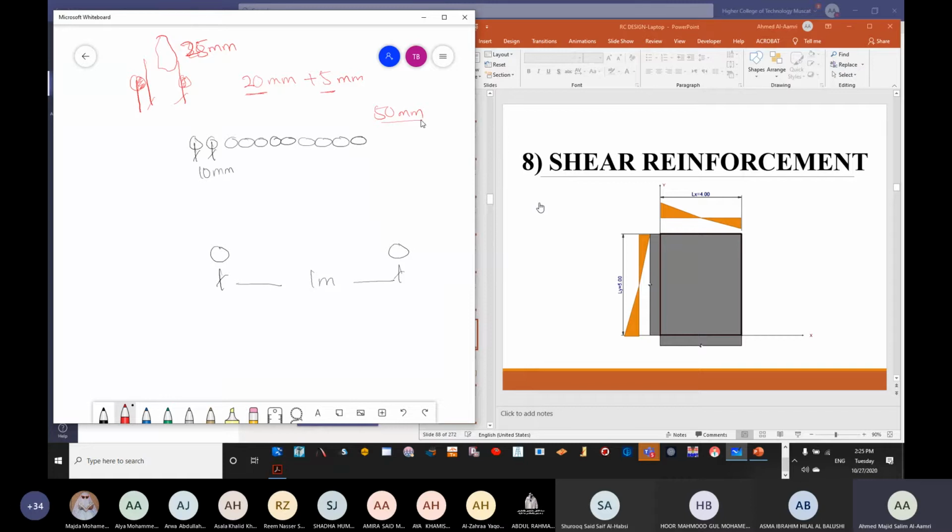And the same thing, 300 or even 400 is going to save you from the issue of maximum spacing. If you're having 1 meter between the bars, cracking is going to happen at the center. Something similar to holding an A4 paper and holding an A0. You will see an A0 is going to deflect because of the distance. In order to avoid that, you need to keep an extra support, which is representing a bar here. So the 50 and the 300 ensure that you are not exceeding the maximum and not lesser than the minimum.